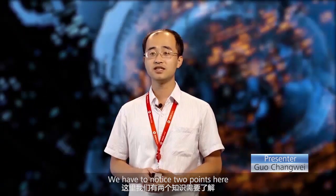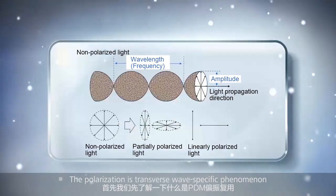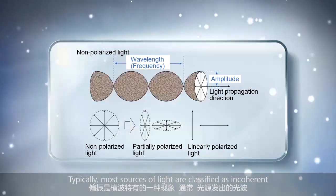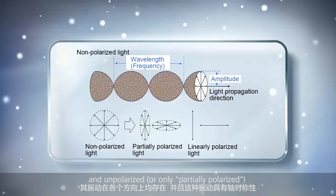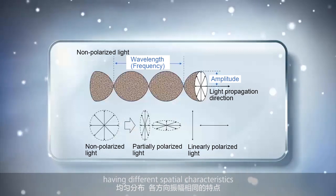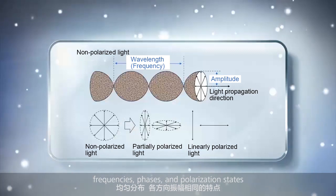We have to notice 2 points here: polarization division multiplexing and dual carrier. The polarization is a transverse, wave-specific phenomenon. Typically, most sources of light are classified as incoherent and unpolarized, or only partially polarized, because they consist of a random mixture of waves having different spatial characteristics, frequencies, phases, and polarization states.